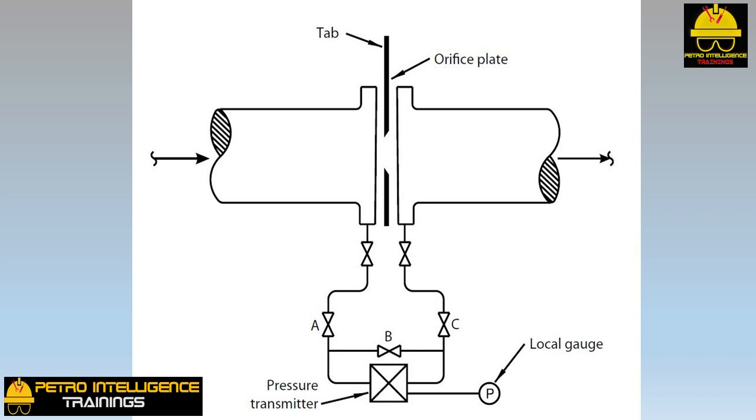If you are measuring the flow of a single-phase liquid, just open valves A, B, and C shown in the picture for a few minutes. If you are working with vapor at its dew point or wet gas, there is a problem. If the flow transmitter is located below the orifice flanges, you will have to wait until the impulse lines refill with liquid. Open valve B and close valves A and C. Now wait until the flowmeter indication stops changing. It ought to go back to 0 if the lines are refilled.